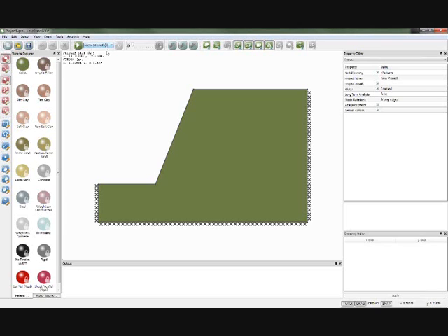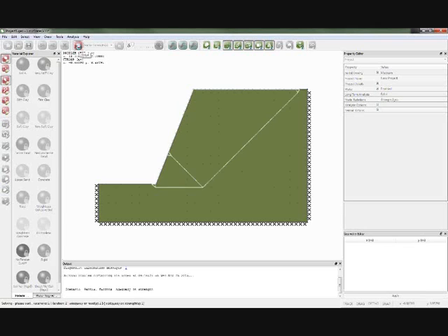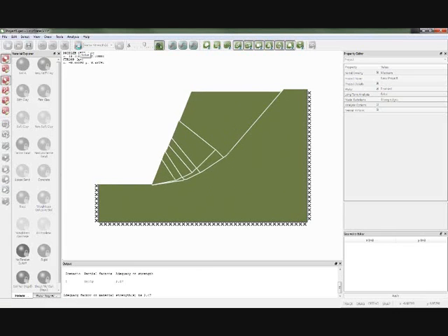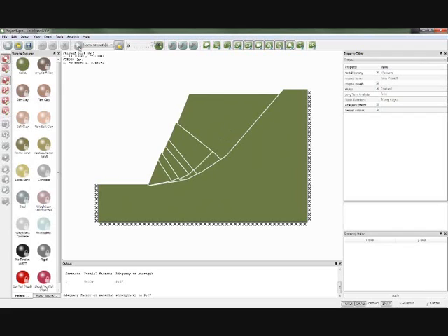Factor strength is the mode that we're most interested in for slope stability, and the software will simply tell us how much the strength of the soil has to be reduced to cause collapse. In essence, that's a factor of safety on strength, which is a typical number you want from slope stability analysis. So I click solve, and in a few seconds it comes up with a critical collapse mechanism, and that's very similar in form to what you'd see from a Taylor slope stability analysis, although in the Taylor method it's a simple slip circle, and we get an adequacy on strength of 2.47 down here.